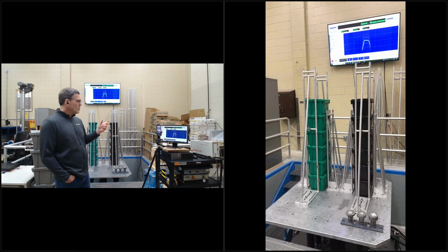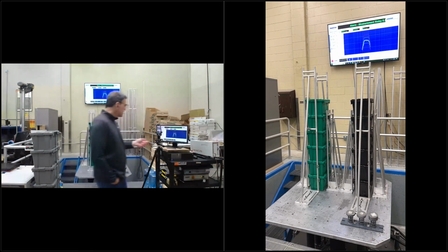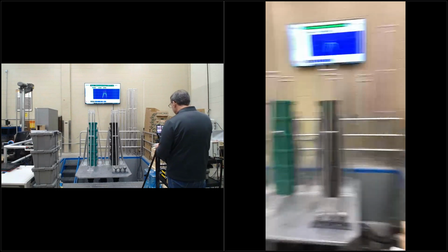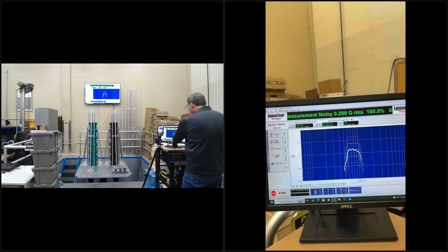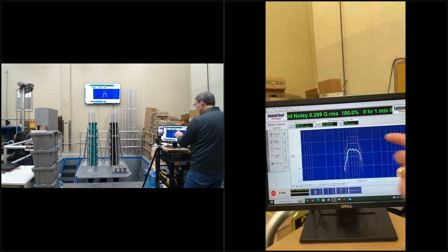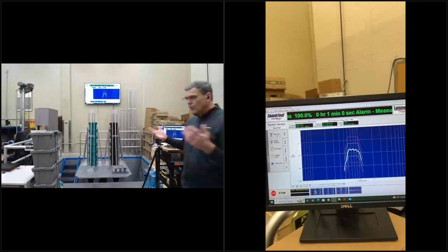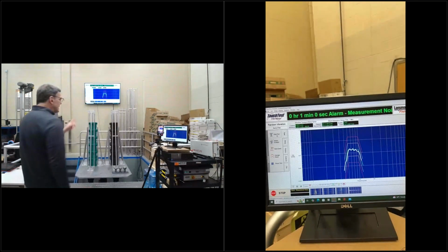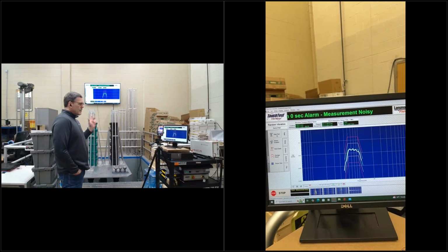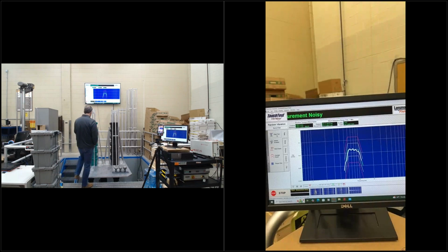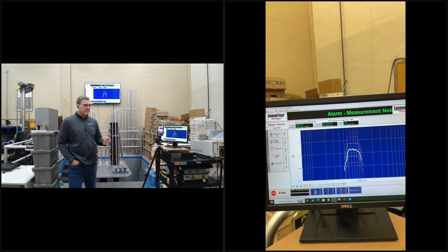In some of these profiles, like this example here that I had on the screen, now this is not a real profile, but if this was a profile representative of some weird transport, I'd be asking for problems shipping either of those stacks in that environment. So I would want to do something to change their natural frequency characteristics, whether it's by changing the load, how I stack, or whether I unitize, and that certainly translates into the bare product, the product design.